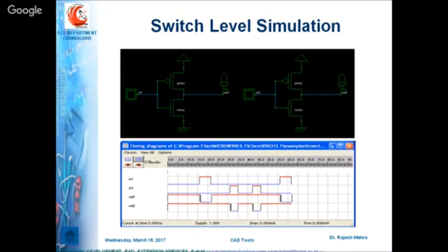And when you make a transition on your switch from 0 to 1, the PMOS will work as an open circuit, and your connection with VDD will be disconnected, and your NMOS will act as a closed circuit. Your output is now connected with ground, and the output LED will be low. So whenever you provide a 0 to the input switch, you get 1 at the output, and when we provide 1 at the input switch, we get 0 as the output. So from here you can see that this circuit is working as an inverter.